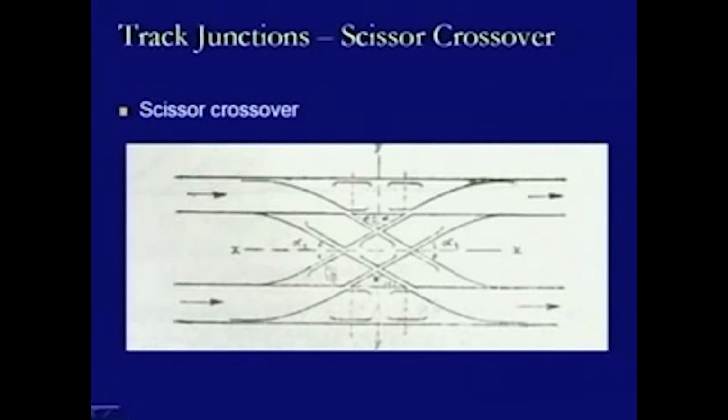So, this is the way we use the same rail section to become a wing rail or a lead rail at the same point of time. Here again, this wing rail is extended, becomes a part of the diamond crossing, and again becomes a wing rail on this side where another acute angle crossing is provided.